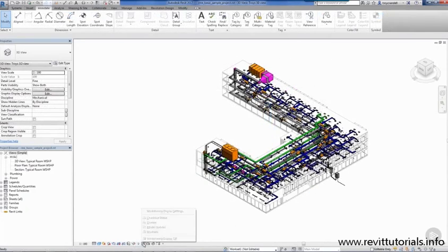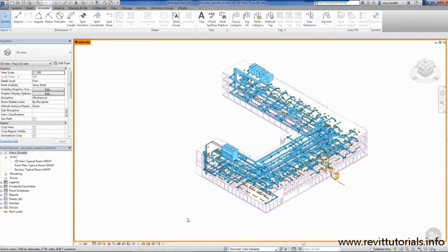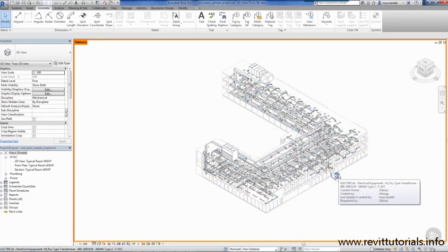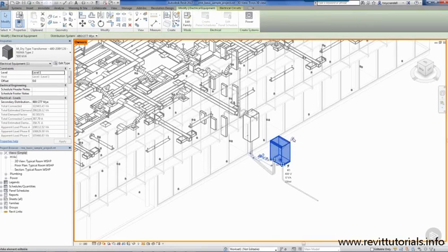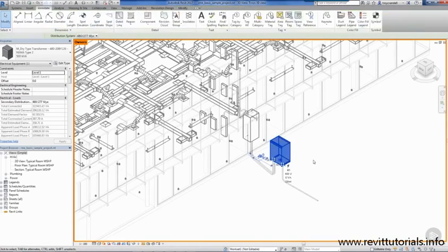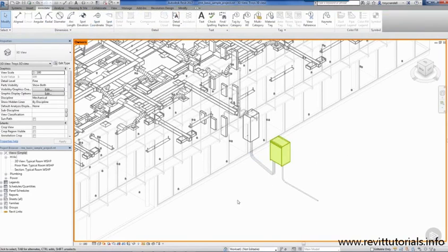Work sharing display is only available when work sharing is enabled. There's tons of useful information you can get from this feature. Clicking on the worksets mode displays a different color for each workset that's being assigned to elements in this view. Now, if I select the owner's mode from the list, you'll notice nothing is colored. Well, that's because no one owns anything yet. So if I zoom in here and then click the Make Element Editable icon, you'll notice the element turns a bright yellowish green color.